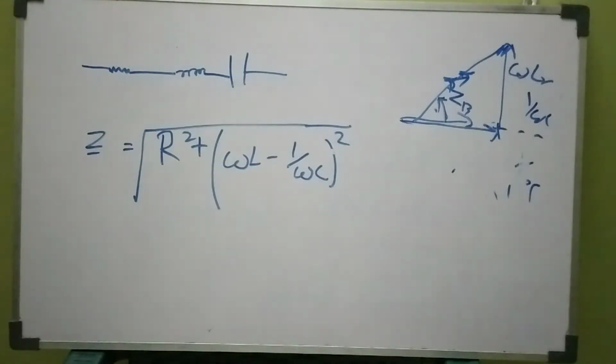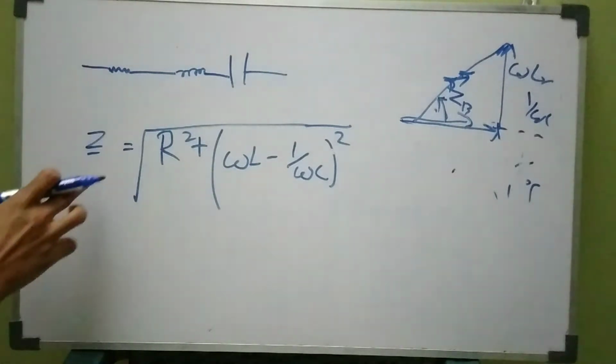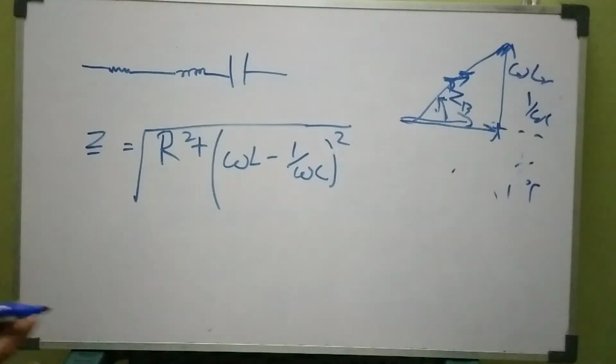The question is whether we need to find these things. They have given the voltage, and at omega equals 1000 radians per second, they have given the current value as well as a phase angle. So when we are connecting both of these data, we always need impedance. As we all know, V equals I times Z, so we need to find the value of Z first. Do we need to find this angle? Yes, because we need to get three equations.